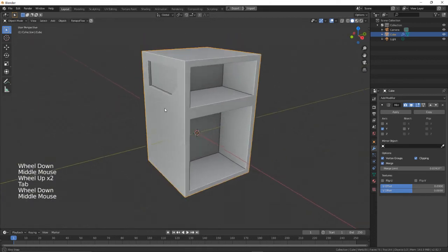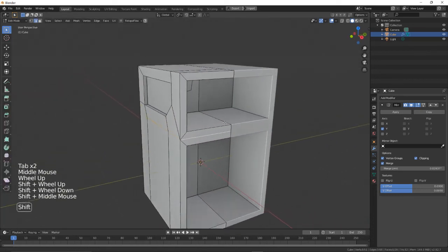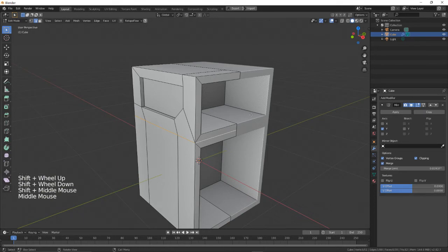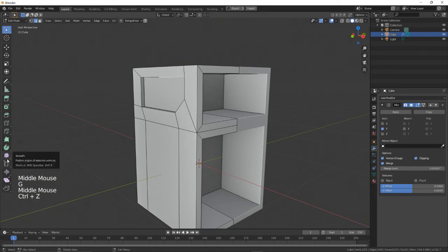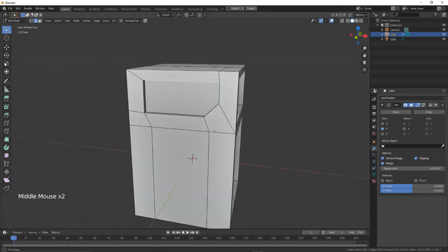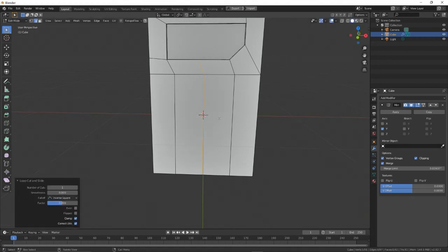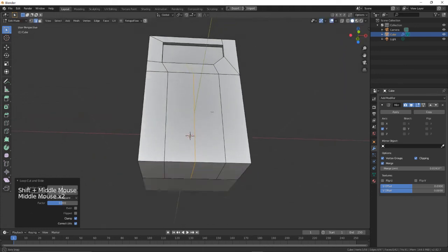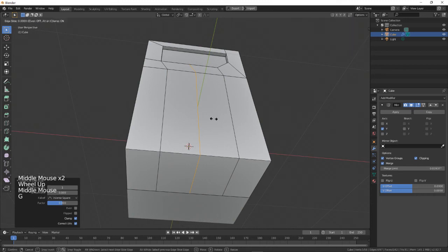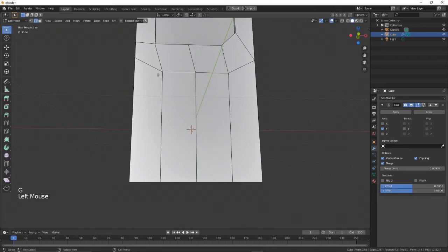So I believe those are the basic tools of modeling within Blender, at least box modeling. You of course have more tools over here that you can see, such as ripping, where it separates the vertices, or smoothing, and probably the most important one I should have mentioned earlier is edge slide. So if I place in an edge loop here, instead of moving it back and forth and possibly messing up the UVs, if I press G twice, then it'll edge slide along all of its relative location, or relative to wherever it's trying to go.